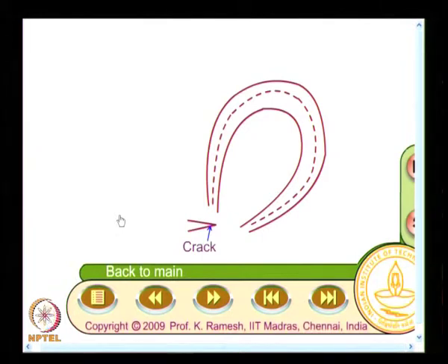So, my scanning has to be done appropriately for each of these segments. A simple horizontal or vertical scanning will no longer be sufficient. It was sufficient because we had fringes essentially horizontal or vertical, but in a generic problem, once we developed a methodology, I should be able to apply it to fracture mechanics problems.